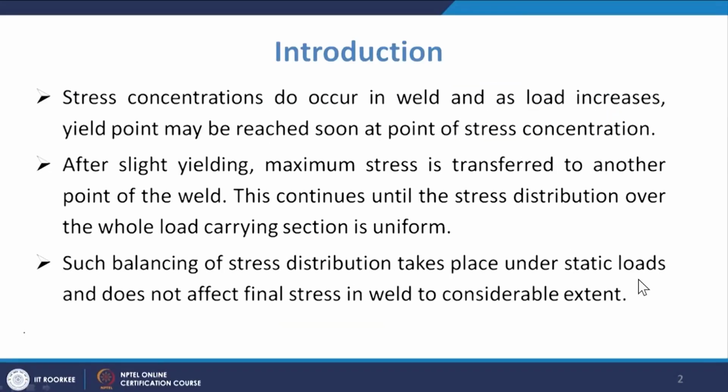the stress concentration that does occur in the weld, and as load increases, yield point may be reached soon at a point of the stress concentration. After a slight yielding, the maximum stress is transferred to another point of the weld.